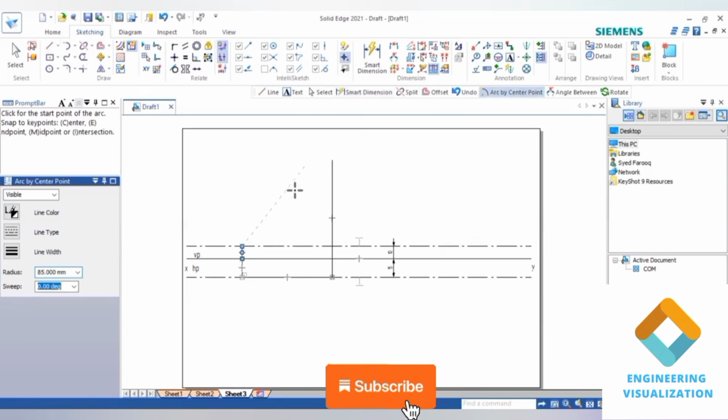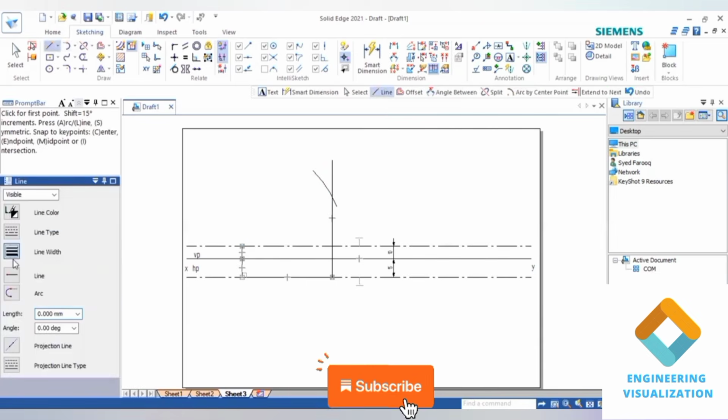Go to arc by center, give true length 85 and cut the arc. Okay, because apparent length when it is rotated and projected we get the true length here. Okay, now you join from this end point to here.